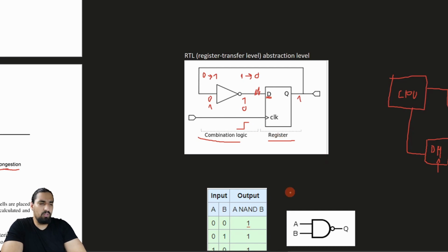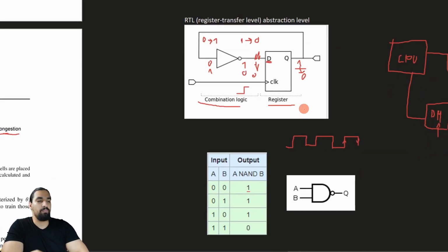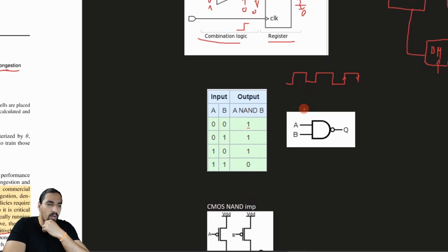And hopefully you know what a clock signal is. It's something that drives your computer. It's basically a digital signal that goes from 0 to 1 with a certain frequency, and on each of these upticks or downticks, something is going to happen. So on each tick, the sequential logic gates, so these gates like flip-flops, will change their state. So if you keep 1 here, and then the uptick comes, at that point the 1 will propagate here. And if you change it now to 0, and the downtick comes, for example, then this will go to 0. So they have the memory. That's the main trick. So having said that, let me go even deeper.